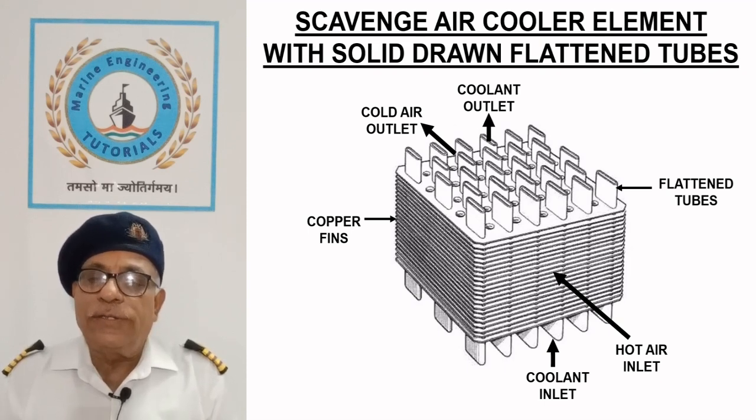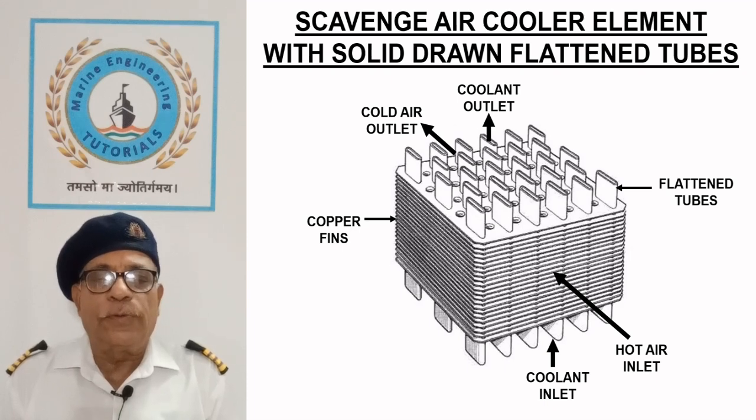On smaller engines such as generator engines, the whole cooler is removed from its air trunking for cleaning on the air side, whereas in the case of large propulsion engines, arrangement is provided for chemical cleaning in place. The water side can be inspected or cleaned by removal of the water boxes and brushing through the tubes.